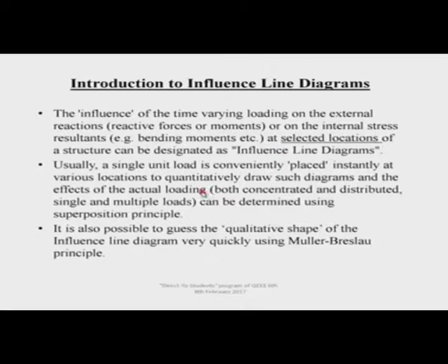Now, what should we do? The loads will vary in structures. So, let us form this proposition in terms of a unit load. If we deal with a linear structure, and we are interested in the response due to the loading, and the Maxwell superposition theorem and others are valid, then it will be judicious to form such diagrams in terms of a unit load, and later do something so that the effect of the actual loads can be determined very quickly.